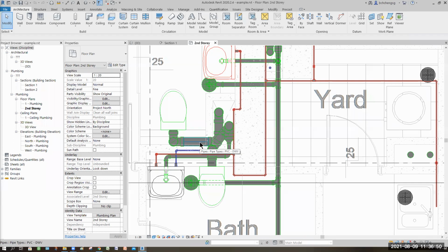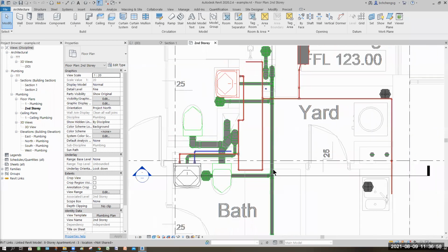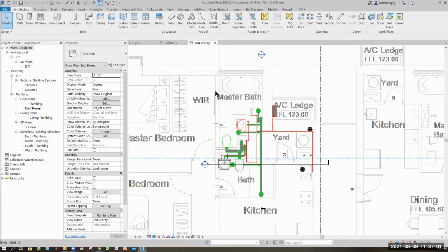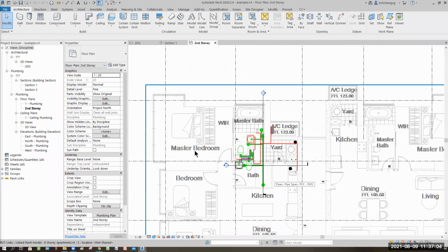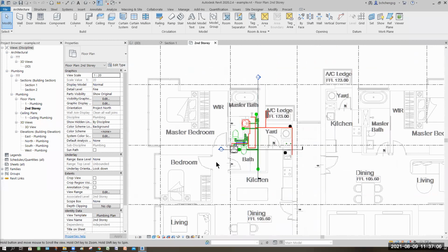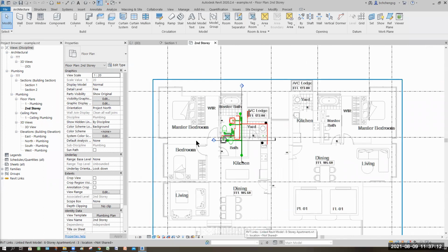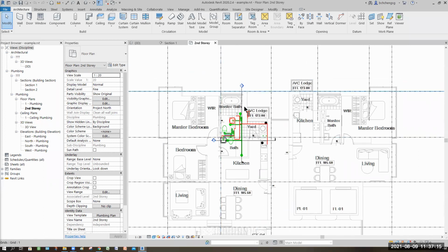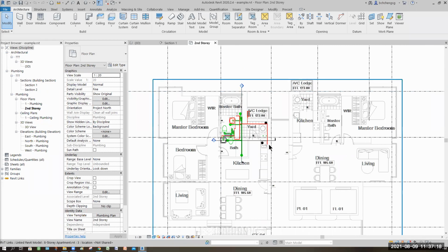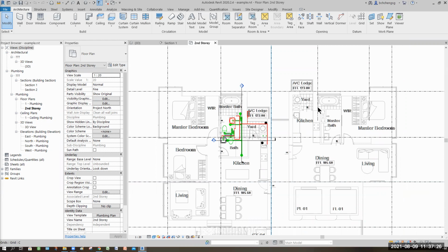Is there a way to check whether the column is load bearing or something? For this model, when you see all these big columns, they're all load bearing. That means one here, two here. That's why I say you need to open the architect's drawing and check it out. This is load bearing. 1, 2, 3, 4, 5. This one is just a thick wall, but I don't think it's load bearing because below should be a beam, right? Then if next building, this is your column.